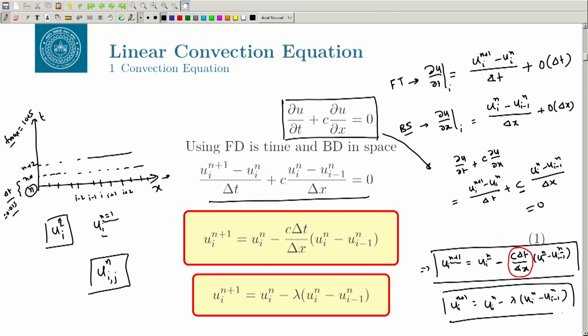And this number has very big significance in CFD. Regardless of what kind of problem you are solving, using RANS approach, LES, DNS, whatever, you need to always take care of this number, which is the Courant number. It is also called the CFL number. I mean, very crudely, if you see what it represents.